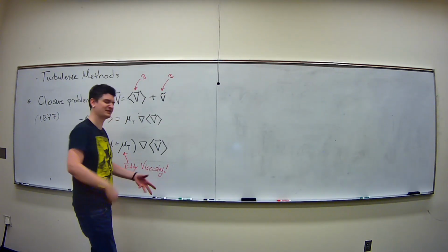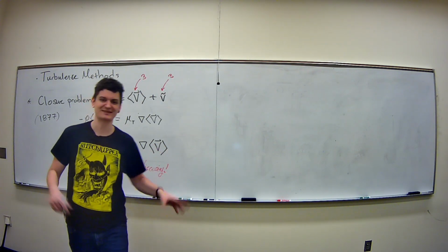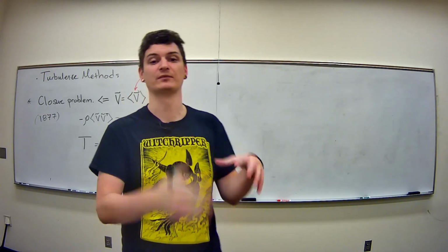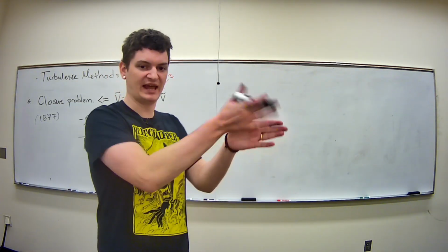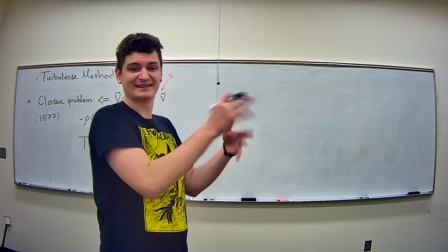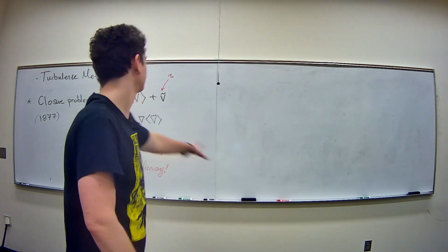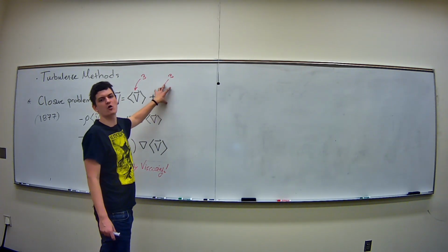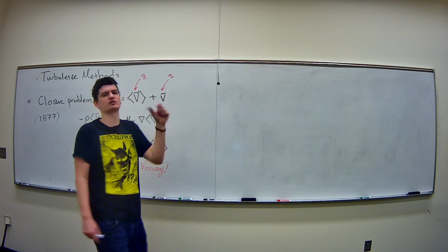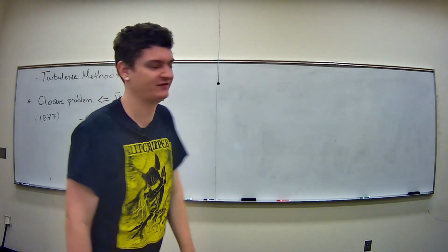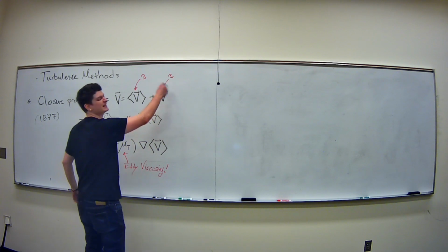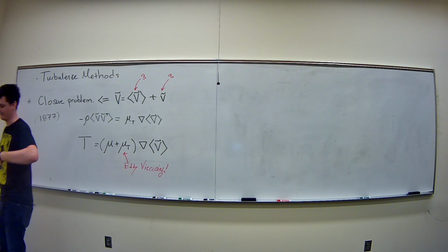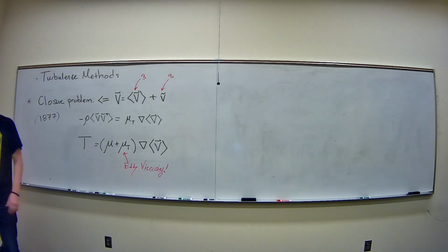Okay, so this eddy viscosity, we're just saying, why did I cross a Reynolds number and all of a sudden everything goes out the window? And it's a property of this three-dimensional stuff, right? Turbulence is a fully 3D theory. You can look at planes in 3D flow and say something about that, but the fluctuations themselves really are coming from the mixture of all axes. There's so much curl you can't quantify in your velocity field that you're just going to model that mixing up of dimensions as some fluctuating quantity that you don't know, but you can experiment to get at. And that is pretty fundamental to this.